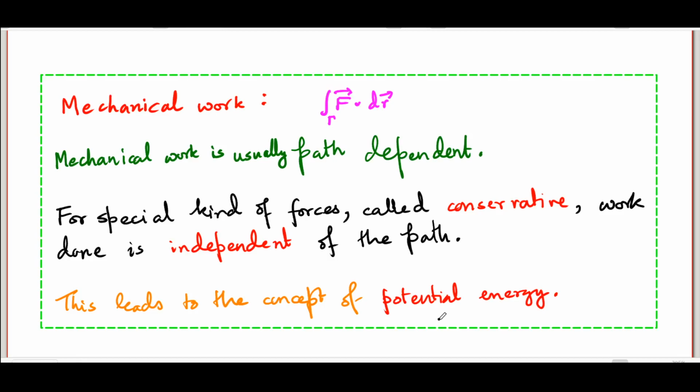In thermodynamics, work done is usually dependent on the path. For a hydrostatic system, where work done is the integral of PdV, the area under the PV curve, that of course depends on the particular path taken to go from a state PiVi to a state PfVf. However, as we have just stated, the experimental evidence shows us that under adiabatic conditions, work done is path independent. This is, of course, the first law of thermodynamics.